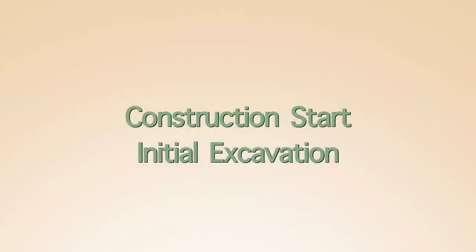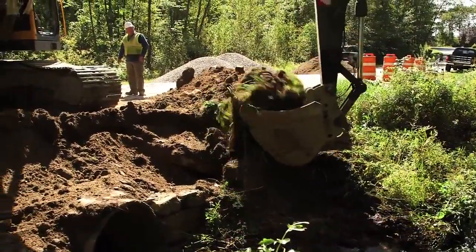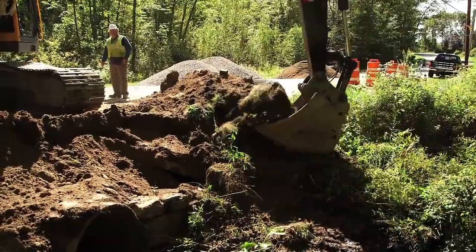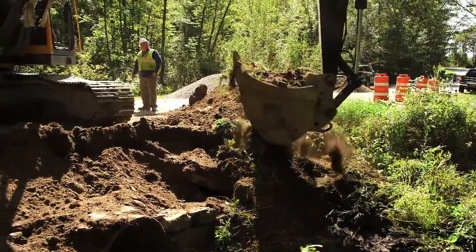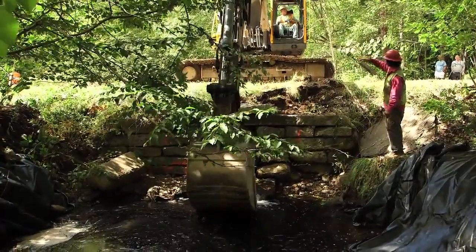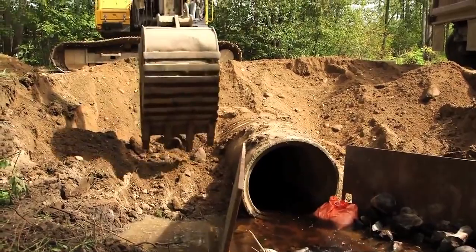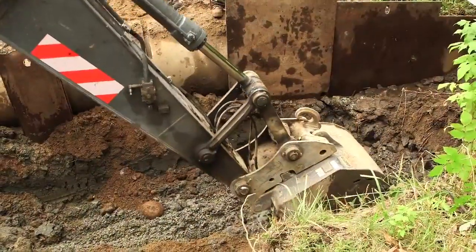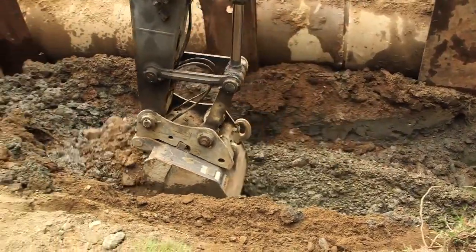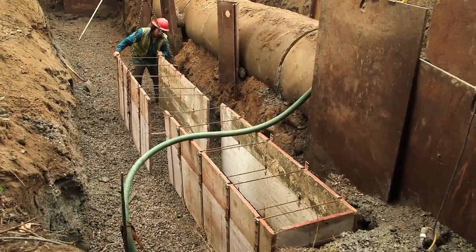Construction start, initial excavation. If carefully done, a large portion of the excavation can be done before the water control is initiated, as long as sediments can be kept out of the stream. For this site, it was most effective to install the downstream sediment basin and upstream steel plates and sandbags prior to any excavation. A portion of the road fill was removed down to the level where concrete footings needed to be constructed.